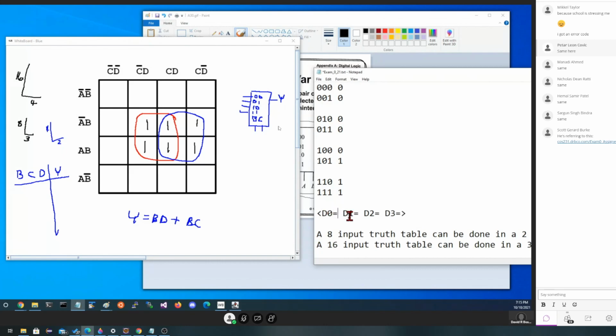So what does D0 equal? Well, in the case where they're both zeros, it's always a 0. The case where they're a 0 and 1, it's always a 0. In this case right here, where it's a 1 and a 0, it matches D completely. So this is D. And finally, the last one is always a 1. And this would be the answer you'd submit to a problem like that. But you would have reduced that thing, which looked originally pretty horrible, down to a very simple multiplexer.